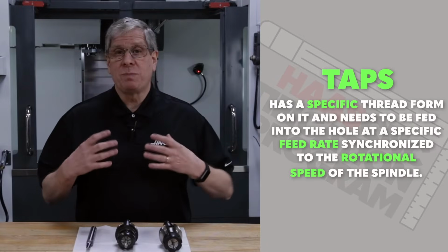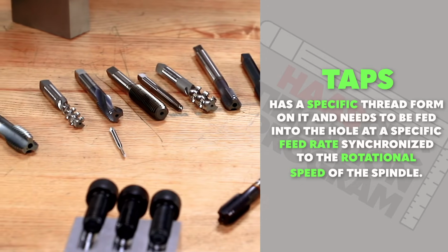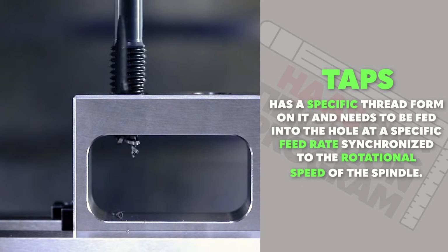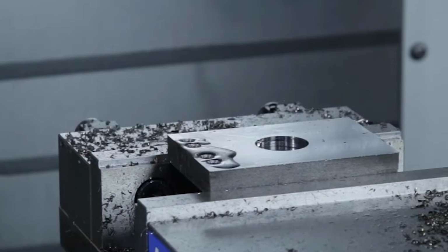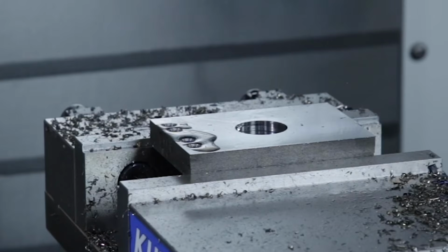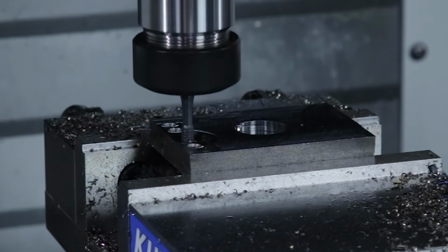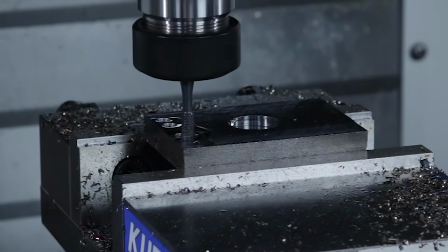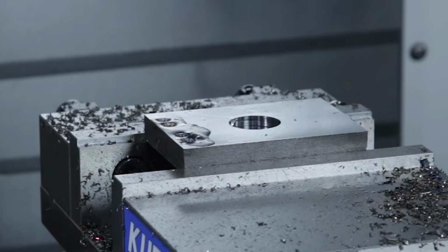The tap has a specific thread form on it and needs to be fed into the hole at a specific feed rate synchronized to the rotational speed of the spindle. The machine has a rigid tapping cycle that synchronizes the spindle speed and the feed rate on the way into the hole and remains synchronized as the rotation stops and reverses to back out of the hole.